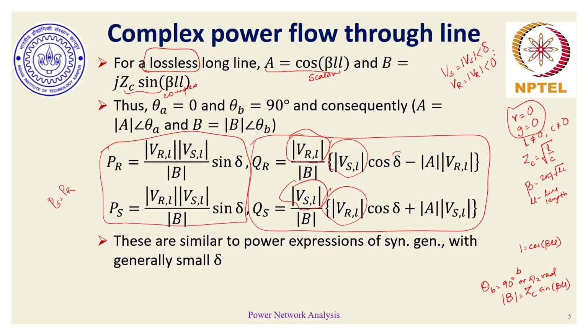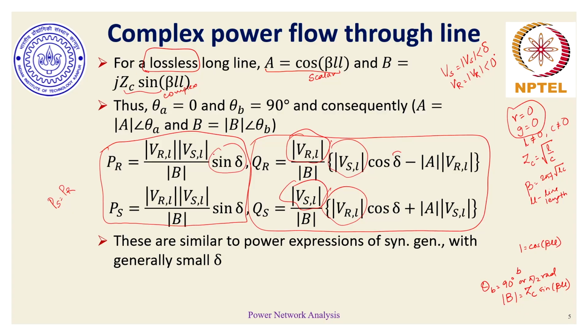And if we take the variation of cosine of delta between 0 to 30, 40 degrees, the cosine value doesn't change drastically, whereas the same could not be said about sine. The sine component almost has a linear variation around 0 degrees for delta. So cosine of delta is a little passive, in the sense that it doesn't have much variation.